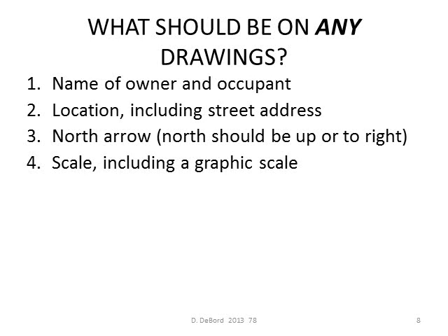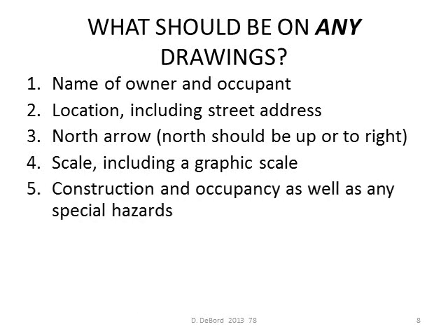These days, we're submitting for permit digitally with PDFs and DWFs, so it's not quite the same, but you need to have a graphic scale so that people can see what the scale is. You could say 1/8 inch per foot, but if it's a half size set, now it's not true, is it? So you need to say it numerically and with a graphic scale so you can actually see what it is.